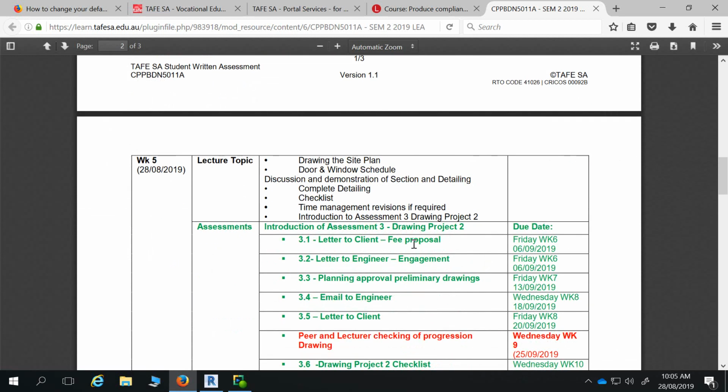We didn't necessarily have to do that in the preliminary because we had the door sizes and the window sizes on the plan. So we probably need a bit more detail now in terms of the schedule to identify if there's any unique materials or sizes, etc. You don't always have to do a door schedule with your submission to council, but you'd need it eventually for builders to start selecting doors and sizes.